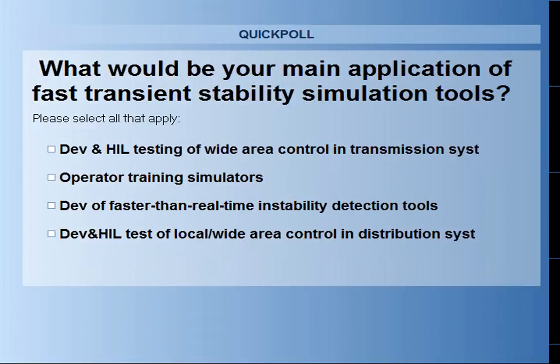ePHASORSIM is a phasor type of simulation, a phasor domain solution. That is, given that we are interested in phenomena in the range of seconds with a time step in the range of milliseconds, we are therefore modeling the entire phenomena around the nominal frequency of the network. And we are modeling the entire problem using the well-known concept of phasors.